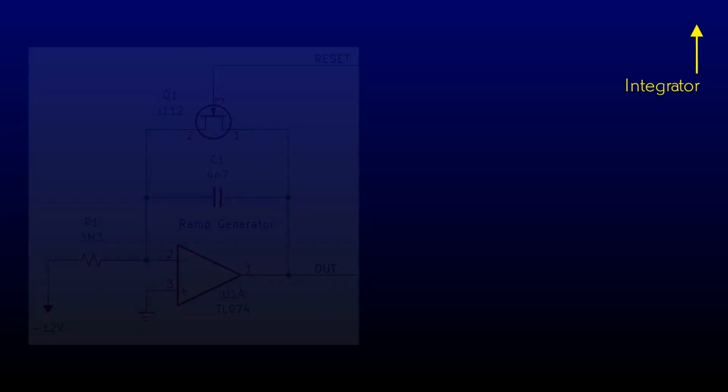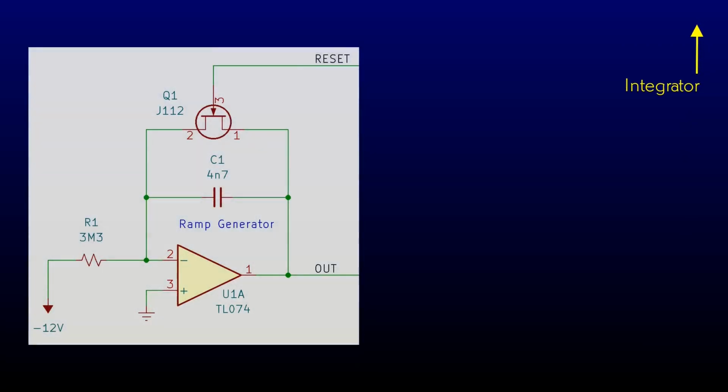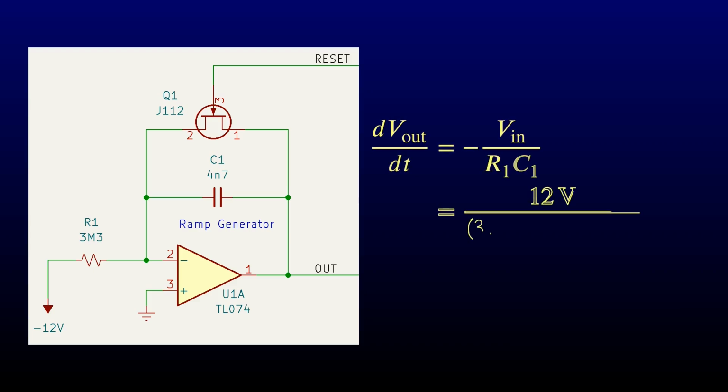The generator for the variable voltage is the integrator that we saw in a recent episode. I wanted to use quite a small capacitor so that it will discharge quickly at the end of a cycle. With the component values shown here, the voltage should ramp up from 0 to a diode drop in a millisecond or so.